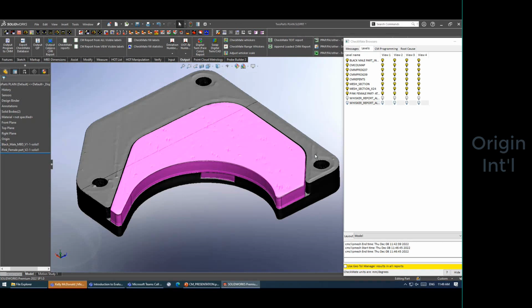Yeah, because there are some things that CMMs just can't do. Some areas on parts that CMMs just can't get at. You can only get so small of a probe diameter to get into a tight area. I mean, there are things that CMMs can still do that scanners can't, like deep geometry. But I think for the most part, unless it's a very tight tolerance part or deep geometry, scanners, again for that 20 to 25 micron range, can now do a great job.